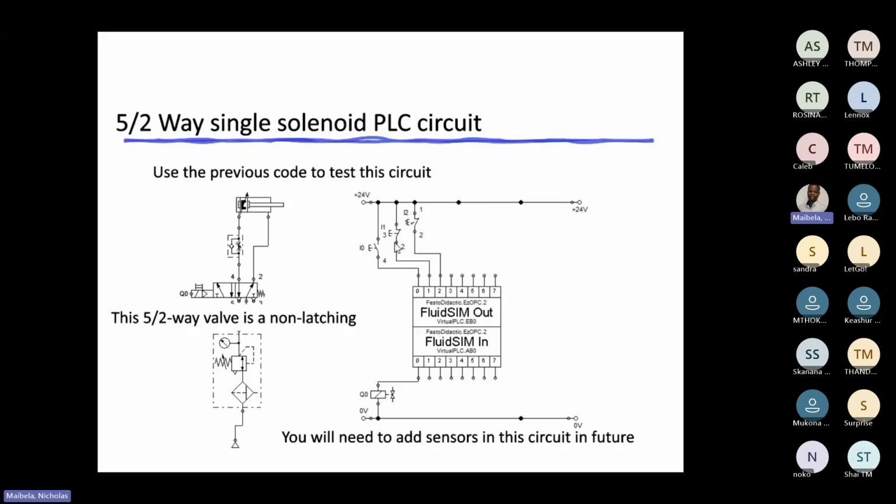I2, the stop buttons, they are normally closed, but there's a difference. I don't know if you can observe the symbol difference. With the emergency stop button, you have a sort of a spike, and with your stop button, it's a kind of T, an inverted E or a T symbol, right? So you have to make sure that your emergency stop button's symbol is like that, and the stop button is like that, right?